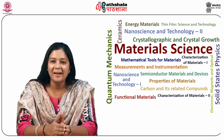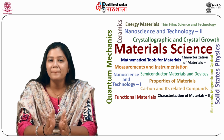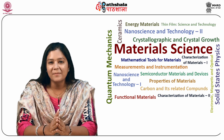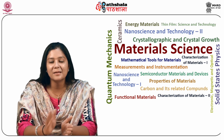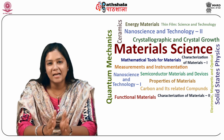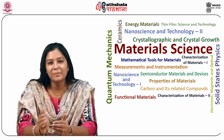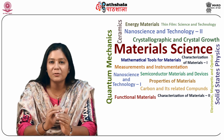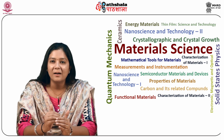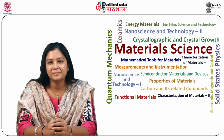Dry reactive ion etching, or DRIE, makes use of chemically reactive plasma to remove materials deposited on the surface. This gaseous form of etching is mainly used for obtaining highly anisotropic etching, a disadvantage of the wet etching process.